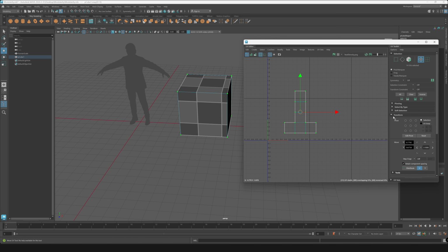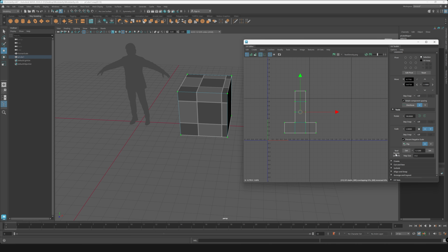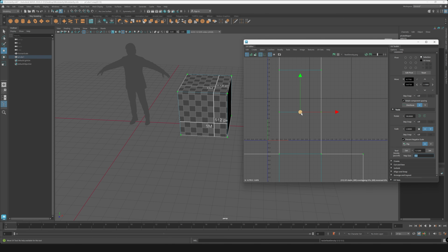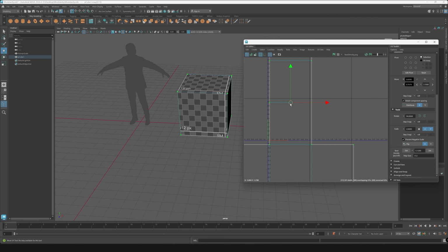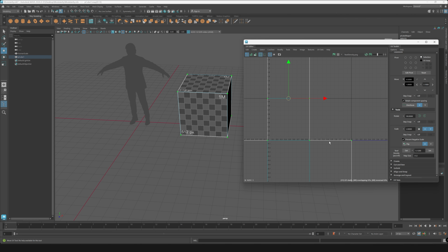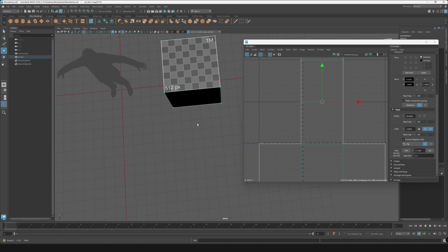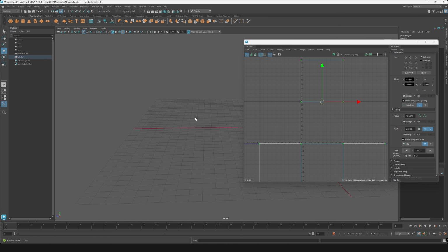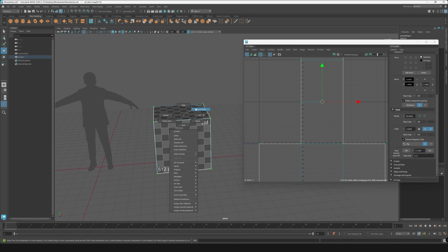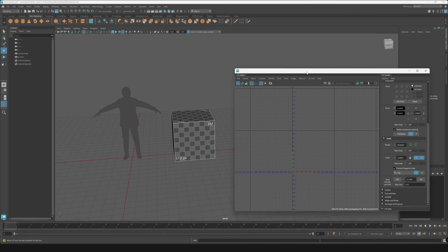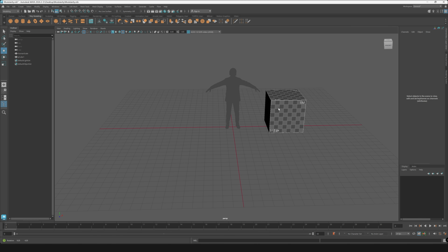Or we just go to transform, go to our texel density checker, set our map size to 512, because that's what the texel density for us is, 512 per meter, or 5.12 units per centimeter. So in this case, we already have that, so let's hit set. And now we just need to snap into the grid. So if you hold X again, it'll snap to the grid here inside of the UV editor as well. And as you can see, now we have a consistent 1 meter scale size for everything. Now we are good to use this for reference. That's what we want to do.